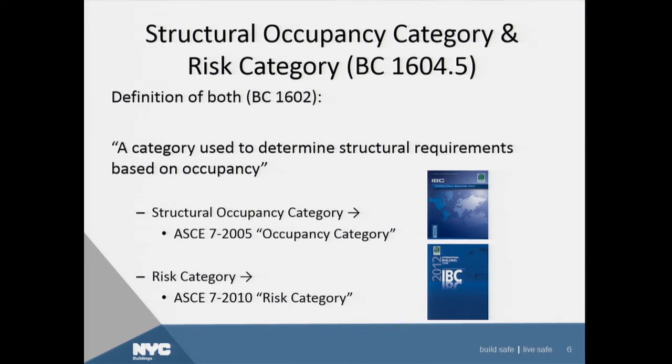We're undergoing a slight change in terminology as far as structural design is concerned. As part of the 2008 code, we adopted a term called the structural occupancy category, which is used in ASCE 7-05 and earlier. They actually call it occupancy category. We added structural to it here in New York to distinguish it from occupancy classification, because we can't have terms that sound that similar. We'll be talking about the wrong requirements if we're mixing up those two terms.